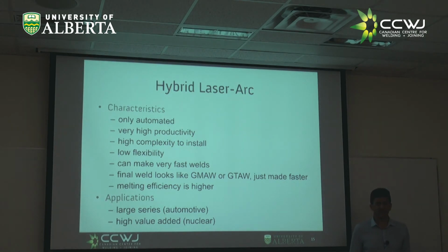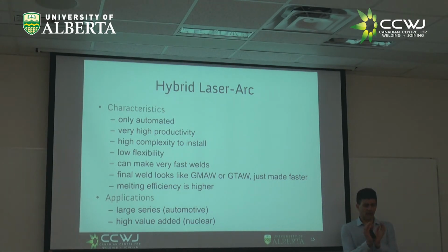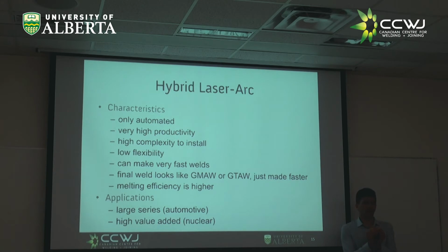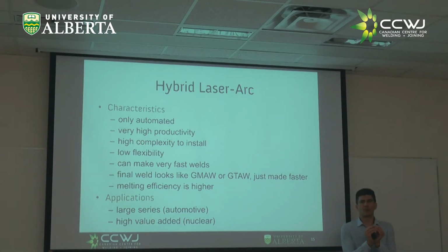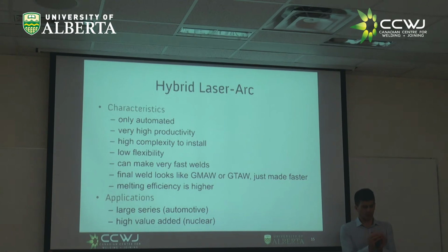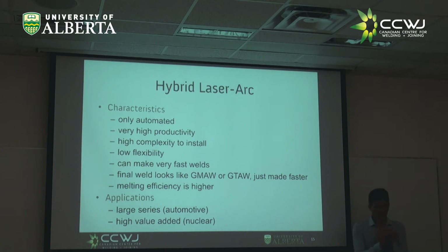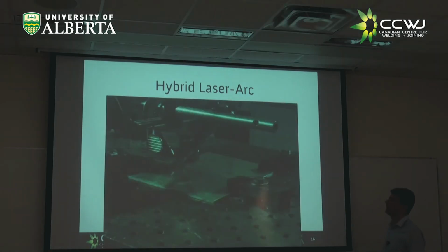The melting efficiency is higher. I'm going to define melting efficiency later, but essentially it says, if you wanted to have a weld of this cross-section, the laws of physics tells you that you need a minimum of heat for that. Now, you always put more than that, right? The ratio between what you needed and what you put, that's the melting efficiency. The funny thing is some things like stick welding, the melting efficiency is very low. So you put lots and lots of heat and you have lots of distortions. But in lasers, especially in hybrid, the melting efficiency is quite high. Applications: large series automotive, high value added, nuclear.